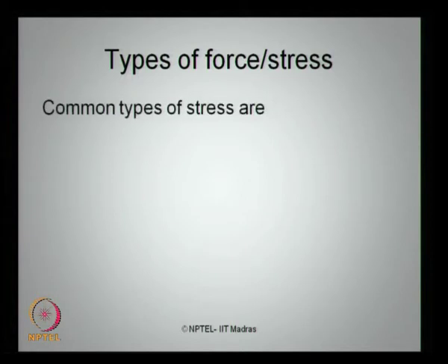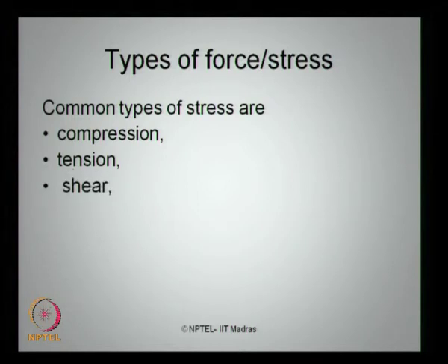There are common types of stresses which can be classified as follows. I can have a compressive stress or a compressive force acting on the member. I can have a tensile force or tensile stress generated on members. We can have shear force coming on the members. We can also have torsional effect on members, and impact forces which can be caused by vessels or tugboats on the members during impact.